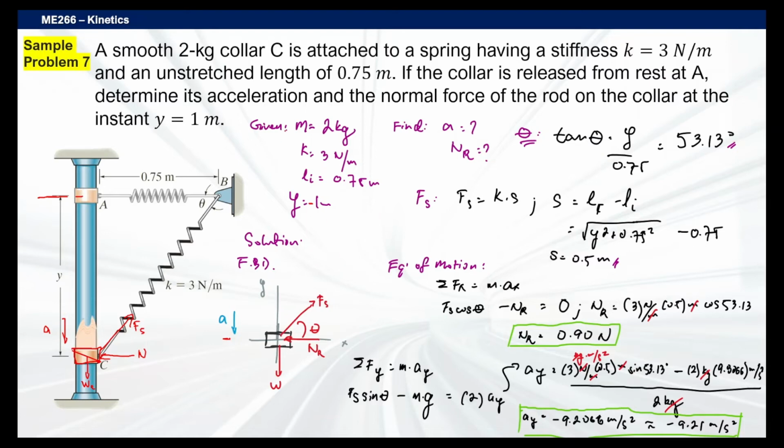So if you can see here, I just established the givens, then established my FBD. And with that, I think I just hit the low-hanging fruits. Specifically, the angle, we can definitely determine that since we have both the x and y values here. And we can determine that via trigonometry. So here we go, the Pythagorean theorem.